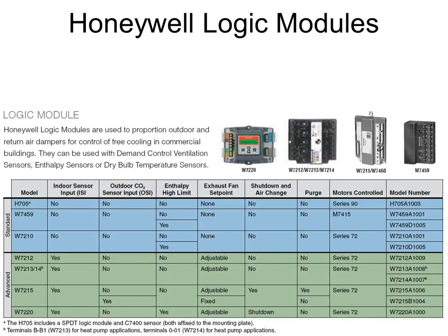All of the Honeywell economizer models are being obsoleted, and there's only going to be one going forward, the W7220, which is the one you see on the top there with the display on it and the green and red and everything. That replaces all the other models that they have. There's numerous reasons for that, some of which involve the staged air volume fans, which we'll talk about next week, and why we have to have that economizer controller to do the staged fans. But it's basically the replacement for everything, and it is capable of doing everything we talked about plus the DCV.